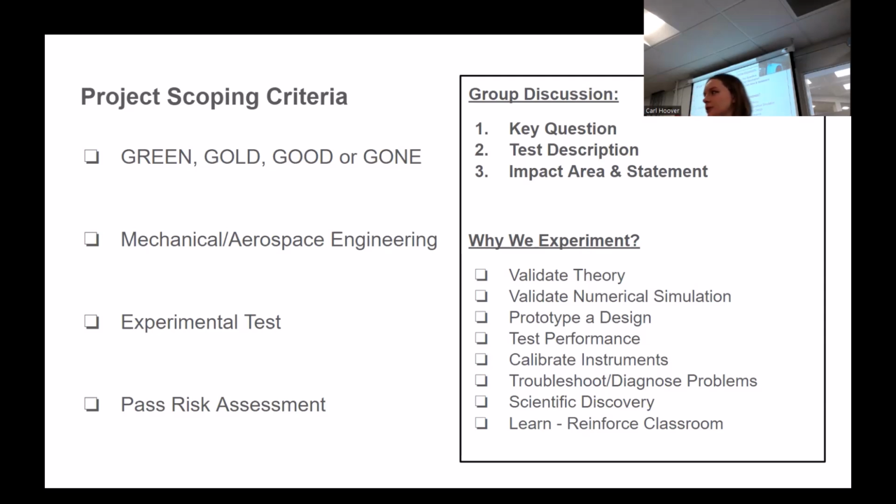So one of the ideas that we were talking about was a common train engine component for the cooling system. It is water cooled, and in colder climates, when the train is idle, that tends to freeze up and cause freeze damage. So something I've been working on for a while, the key question would be, how can we detect the temperatures within that cooling system without having to make any changes to the pre-existing engine or cooling system? So my idea was we could attach thermocouples to just a piece of cast iron